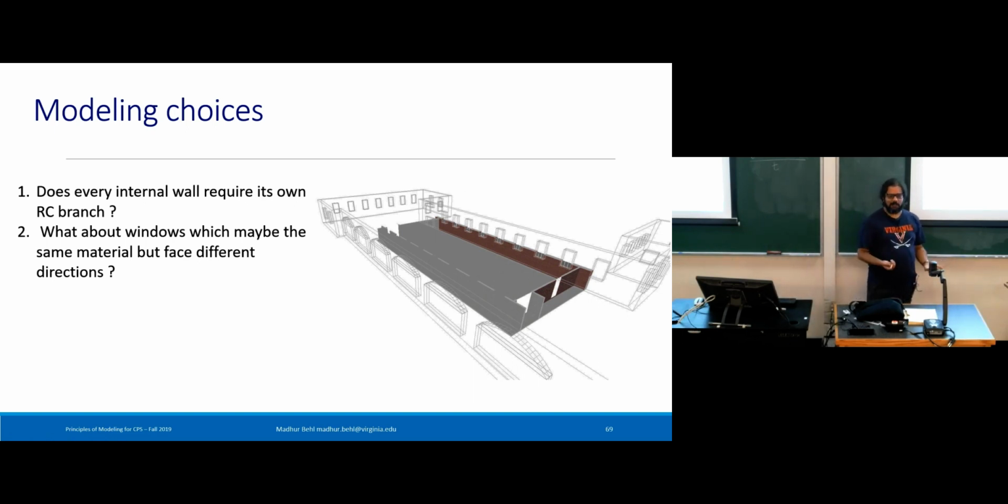So my model just ended up having one resistance to represent all of the windows, not 8 different resistances, right? So it's an aggregation game. The model doesn't care whether you model each window with R1, R2, R3, R8, or collectively estimate the resistance, assuming that the window is the sum of all 8 cross-sectional areas. The resistance of the window depends upon the thickness and the cross-section area. So I can just add all the 8 cross-sectional areas, assume the same thickness, and just represent it by one window, functionally.